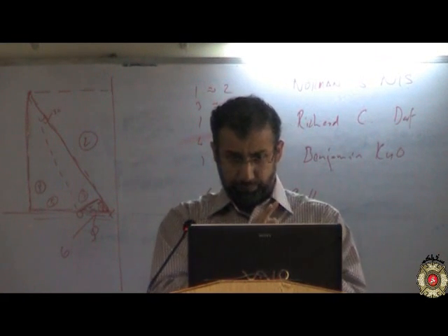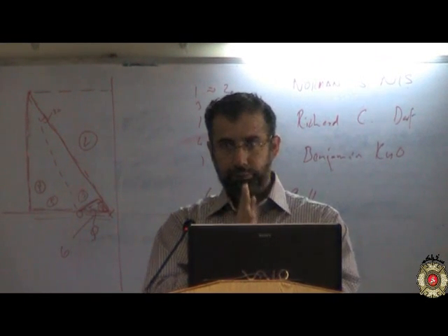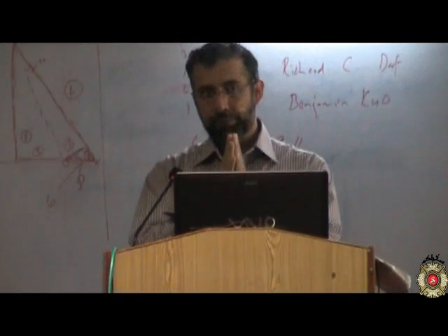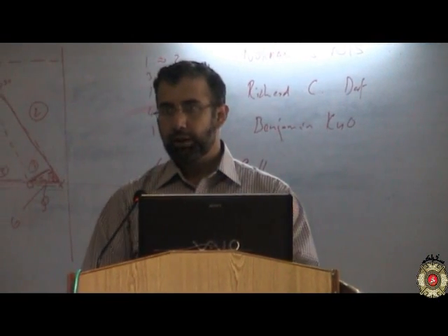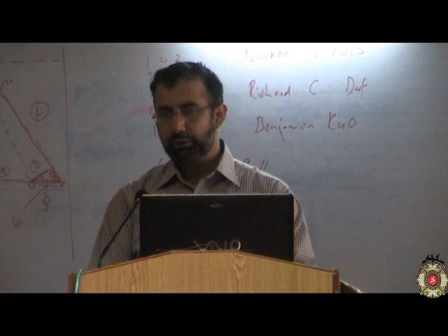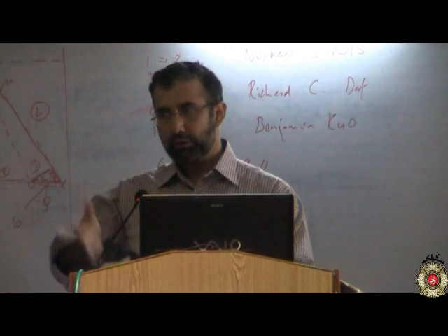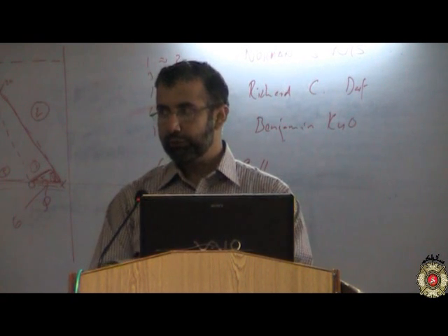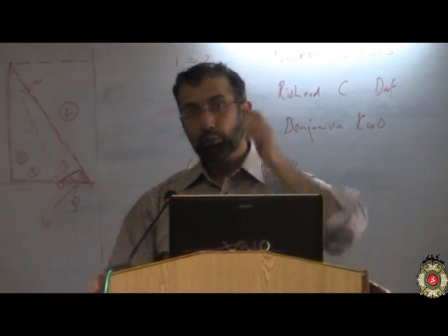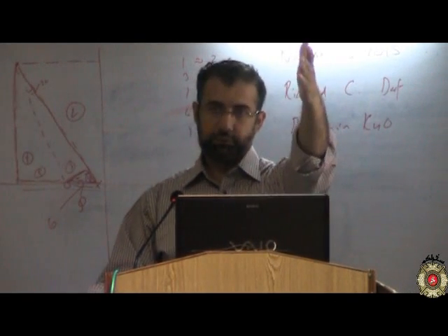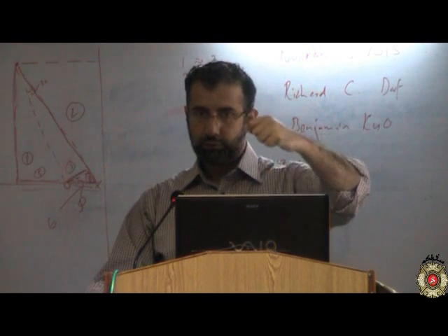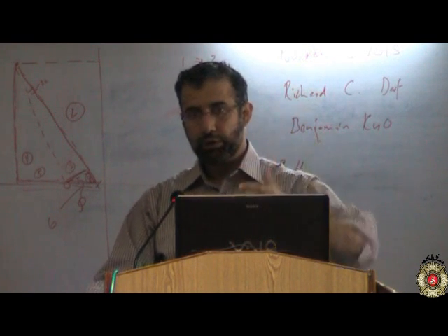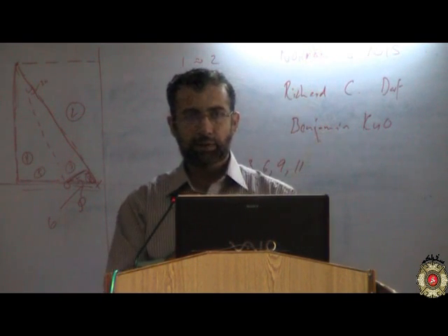As we approach or get close to it, it starts to sense that there is a body up there. And this we covered in chapter 1, where we said that the disturbance also travels at the speed of sound. So the body which is still ahead has sent some sort of disturbance which travels with the speed of sound, so the velocity would automatically adjust itself.